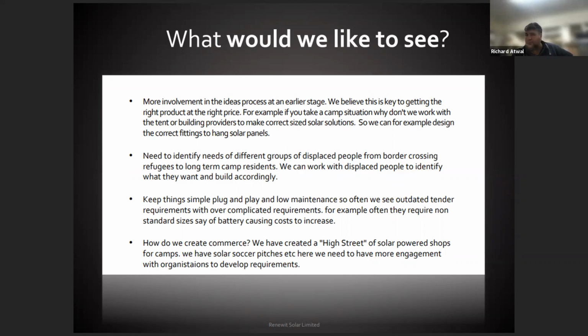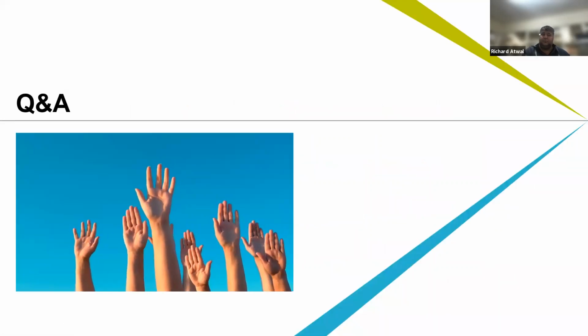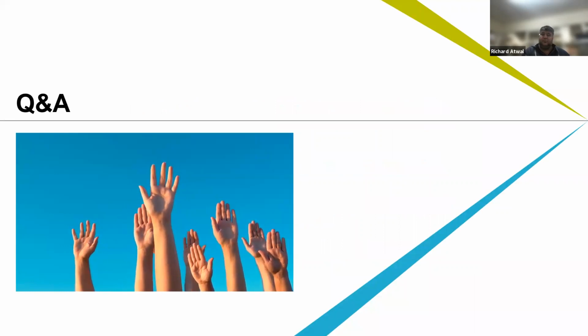As I already mentioned, the optimizer we designed was based on considering the efficiency, and we found the maximum capacity is 130 watt, which can be achieved at 95% efficiency. If we go higher, the transformer needs to be bigger. Here we use a high frequency transformer, and as I told, it is a buck boost converter. So it is a switching mode power supply.